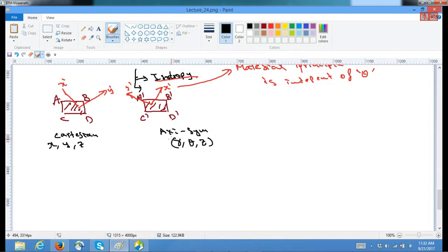So what we'll do is we will not try to solve it from the principle of virtual work, since we have already seen that all the forms remain the same, so we are rest assured that our equilibrium equation, even in the axisymmetric case, would be of the form k u equals f. Only that our u's are not based on Cartesian, but they are based on r theta z, that is ur, u theta, and uz. Right? Similarly, these things also depend upon the formulation.